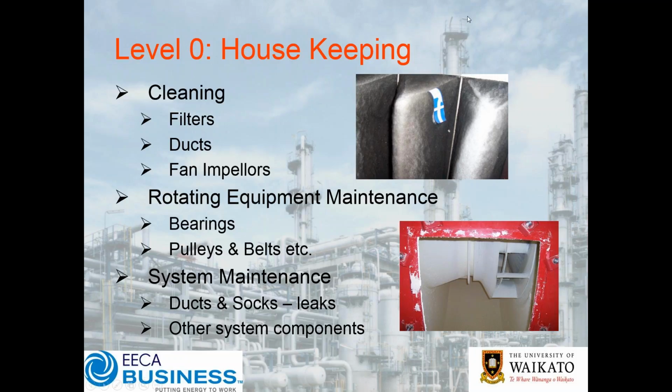The other thing that's a really common fault, and you see it all too often as we go out and about to various sites around the country, both here and overseas, is that it's very common to see flexible socks around duct transitions and the like with big gashes and holes in them. How well are these being maintained? Now, there's an energy loss point of view.